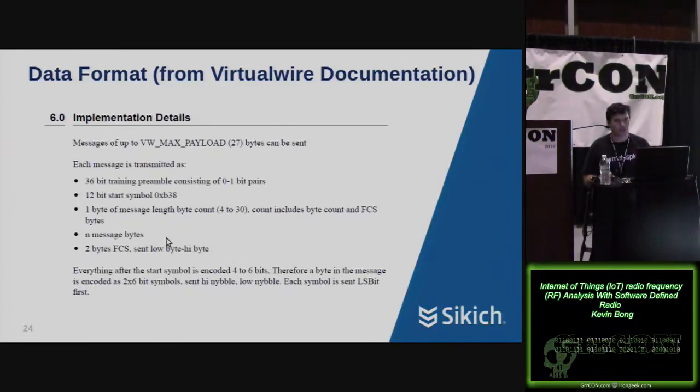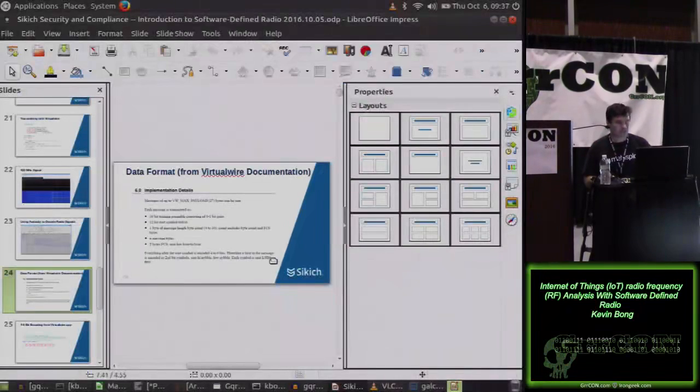So that's kind of how we'd go through decoding this signal. You saw I was cheating because I already knew what library made it, and that's kind of how you'd have to approach a lot of signals that you don't know. You know, try some of the decoders people have already built, but if not, if you're just getting that data, it's like, how can I analyze that data? What does it look like it's doing? Those types of things. So that's kind of first steps into that process.